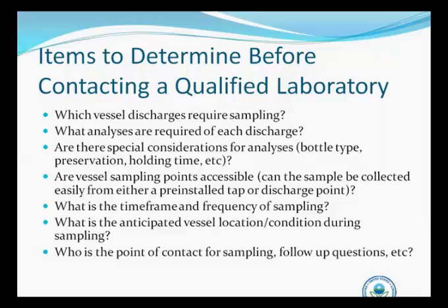In most cases, this has already been done during the construction of the system, but we have attended vessels sometimes where a sampling port was identified early on a diagram, but it doesn't exist. So it's really important to confirm that before you arrange for sampling, that you have an adequate sampling port to draw a sample.